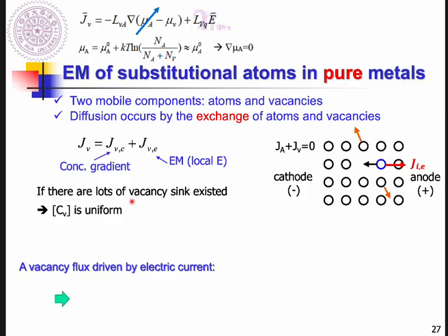So they don't think there's really a concentration variation on vacancy. So the concentration of vacancy is uniform everywhere inside the material system. So this term, JVC, usually people don't believe we really do have a vacancy flux. You cannot really visualize the vacancy flux passing through your materials.